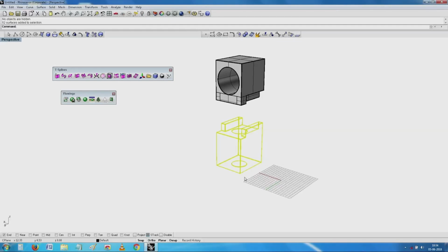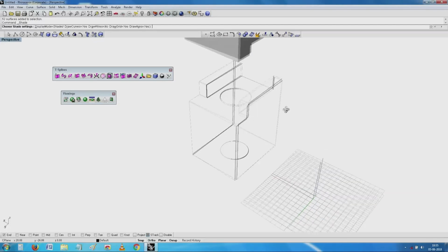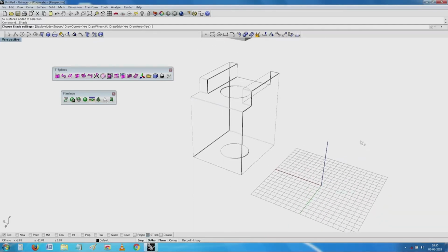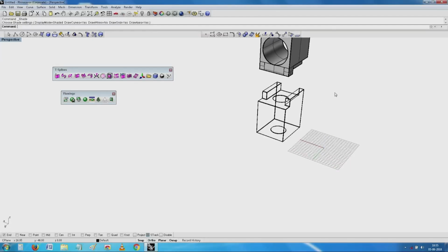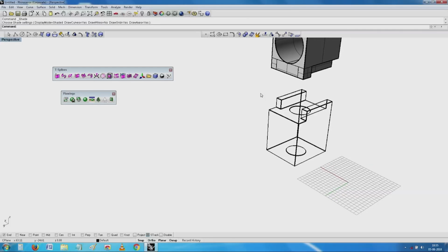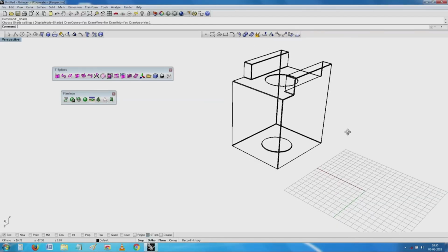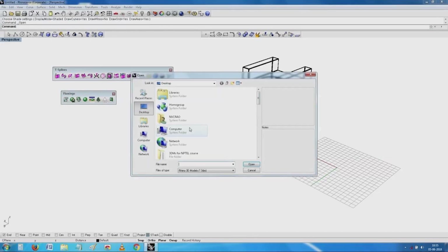See here, the bore should have been through, like what is shown here. For the purposes of convenience, I have hidden all the faces so that you can see the object as it is. Now, if I make the bore through this and also make the steps, building it will be very easy. Probably one of the easiest objects that I can build would have been this. So I just wanted to show you this as a way of handling bores in opposite or orthogonal directions: you need to split the object into parts, and when splitting, location is also very critical. So I have a nice, very convenient thing here, and I will say it works extremely well.